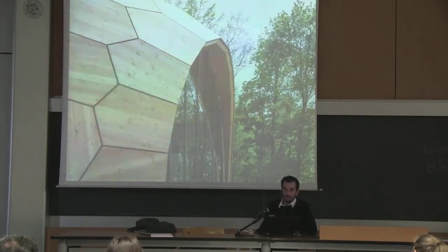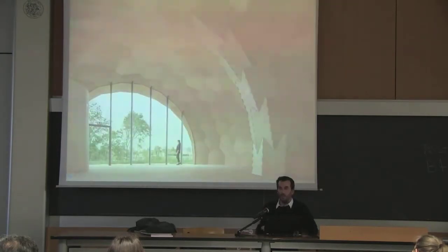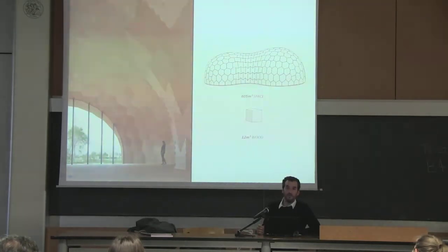So I think it's interesting to note the high level of coordination between the plate morphology and the facade elements, which I think is evidence of the ability of the agent system to derive that. And it's also interesting how this distinctive shape of the blades becomes a key architectural feature for a space that has a central contraction and then opens up towards this space that opens the view towards the landscape. And again, I think it's interesting to note that here the spatial expression does not come at the cost of resource efficiency. In fact, the entire shell could be built using just 12 cubic meters of wood, which was actually utilized entirely because all the offcuts from the plate machining were used as the hardwood flooring.